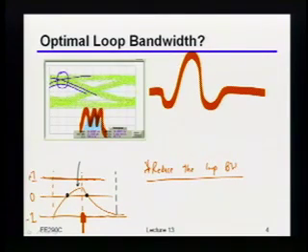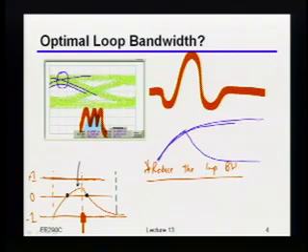That slope is due to the fact that, as an example, if I had a low-pass filtered channel and I leave it as a 1 long enough, versus if I had a 1 and then a bunch of zeros afterwards, those levels are different, right? So now you can see there's a slope on this data here.